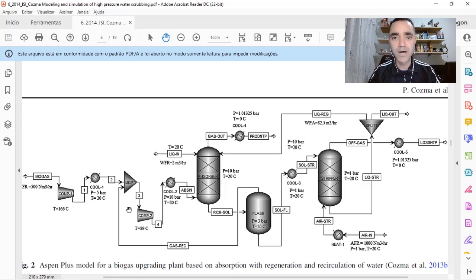If we are talking about a system where the largest pipeline or largest header operates at low pressure, the higher pressure fluid will be able to go inside the lower pressure fluid, and you will not have an increase in pressure, because most often the high pressure fluid has a very low flow, and it will not be significant enough to increase the pressure above 3 bar, or above the lower operating pressure.